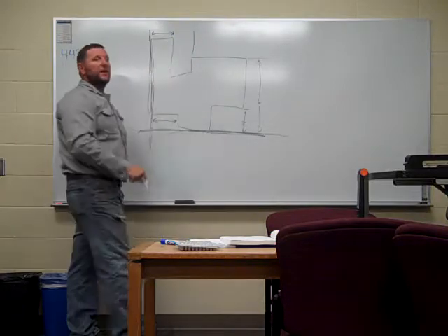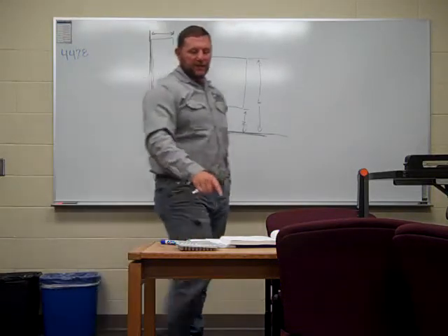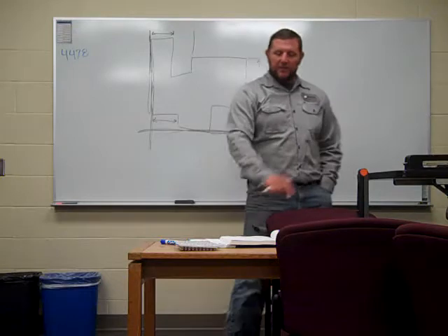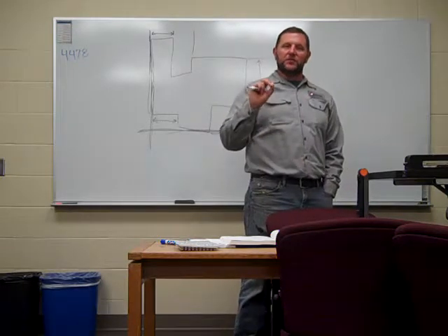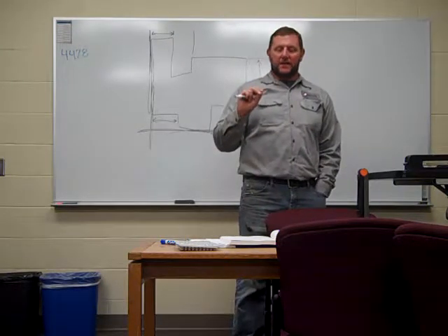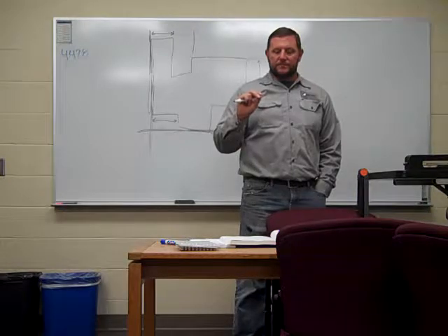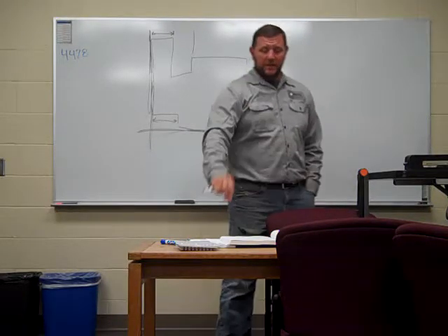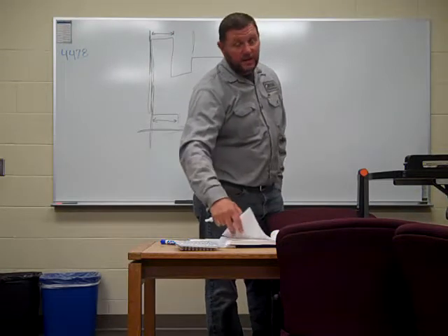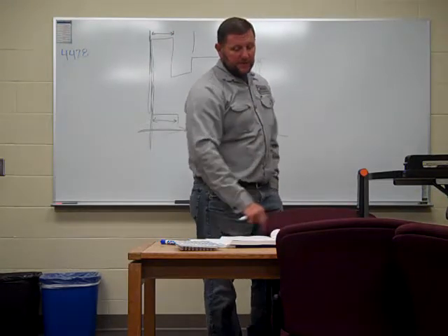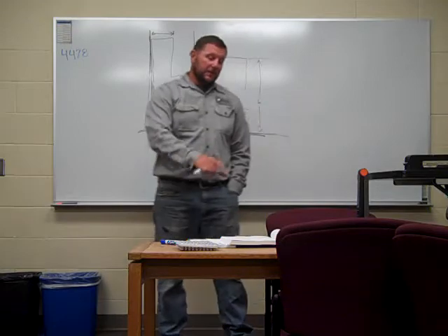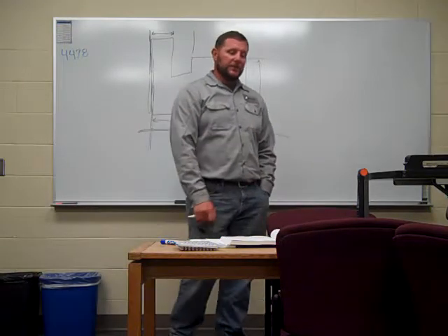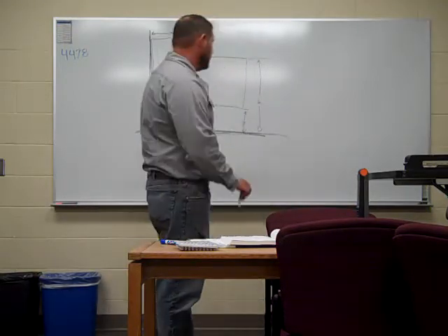As you can see, this gets very cluttered. That's the example of 9.6a. You can see they're bringing that extension line out. Every dimension comes off of that datum reference line. Very cluttered. Very, very cluttered. I've never seen it actually used in industry. Neither have I used the zero plane dimensioning on the following page, on 122.